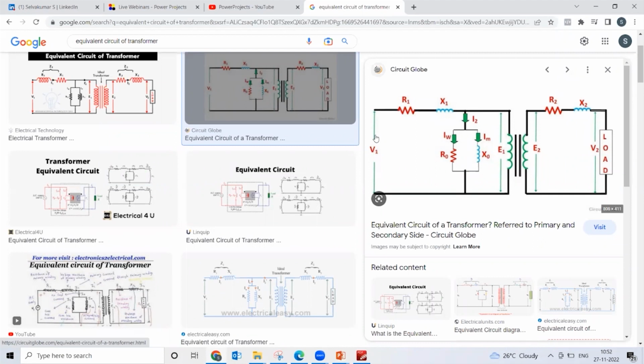So what I mean is, you may need a device which should not be a function of frequency. If you want to measure the actual harmonics available in the line, the equipment you're using to convert one voltage to another voltage or one current to another current should not be frequency dependent. But unfortunately, an instrument transformer is an electromagnetic device and it has predominantly inductance. It has an impact because of the change in frequency.